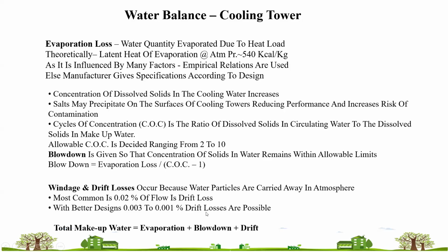in the water. So how can we calculate the total makeup water quantity? We have to calculate the evaporation loss, what the quantity of blowdown is, and what the drift and windage losses are. The total of that is equal to the makeup water. So there will always be makeup water provided to the cooling tower to maintain the level of water inside the cooling tower or in the system.